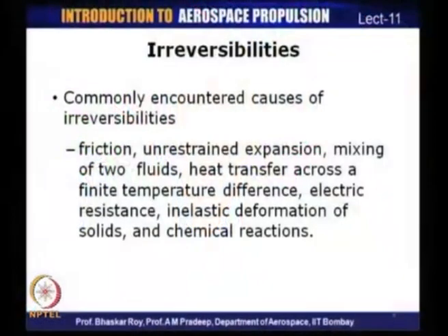To go through the different types of irreversible processes: friction, then unrestrained expansion, which is an expansion across a very high pressure difference, mixing of two fluids, heat transfer across a finite temperature difference, electrical resistance, inelastic deformation of solids, and chemical reactions.